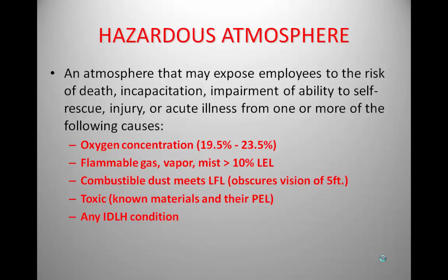Flammable gas, vapor, or mist exceeds 10% LEL. LEL is lower explosive limit. That is a point where something may explode but not sustain combustion. The good news about this is LEL, lower explosive limit, at 10%, it gives us a window of time to make changes. Obviously, you could get into an environment and you're already at LEL. Example being, let's say you have a product X, its LEL is 100. You get into the space and all of a sudden your meter is going off and it says 100 on it.